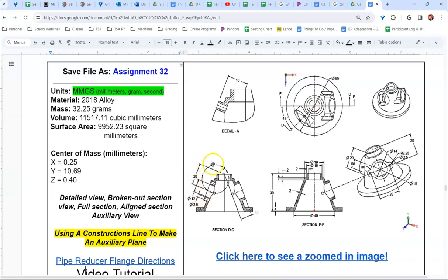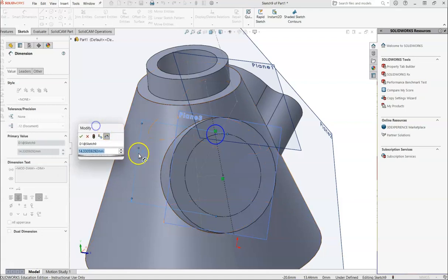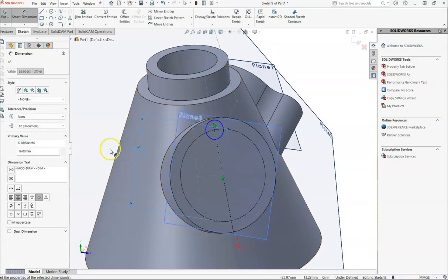Well, if you look over here at this picture, do we see any measurement that goes from there to there? The only other time that it dimensioned something over here, it's got one line that goes from the center out, and it says radius 8. So I'm guessing that this is talking about the construction circle. So the radius is from there out. That means since we're drawing a diameter, we actually want 16. Okay, so that put us out 16.